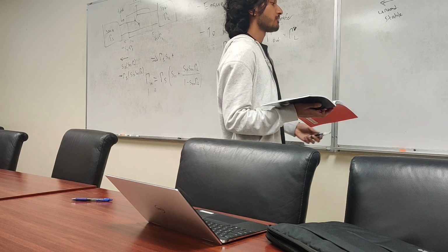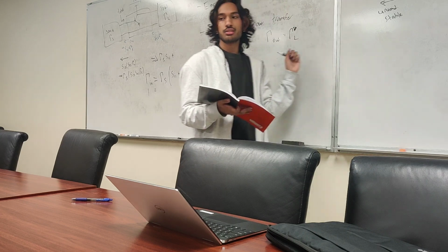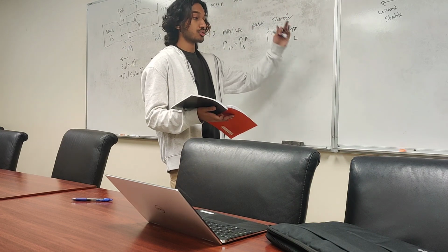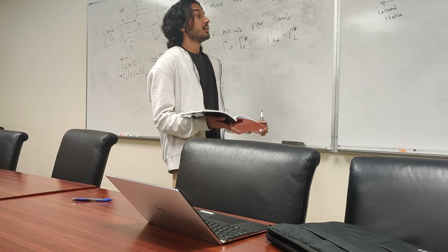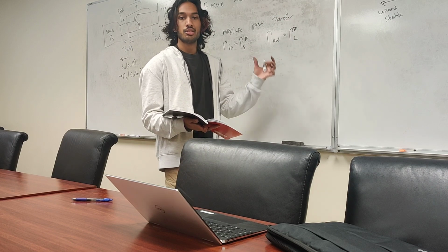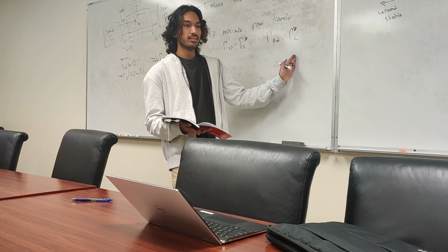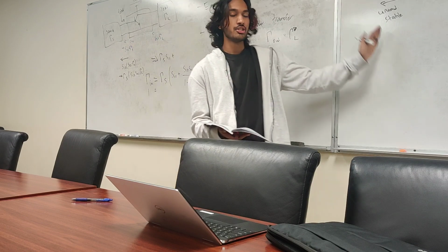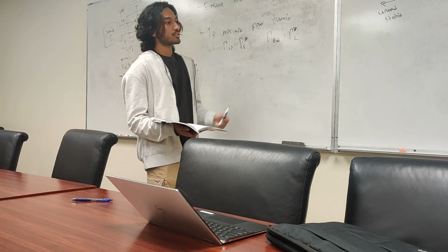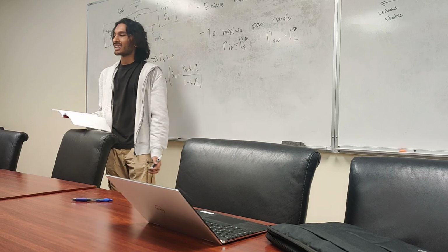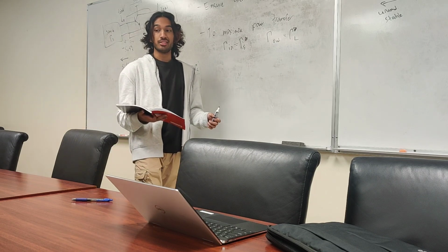I erased it, but you gotta remember that our source and load networks are all the way at 50 ohms. You put things in between to make sure you see 50, and then the other thing that sees your BJT. That other impedance is where your transducer function will be at maximum. That's not gonna be a 50 though, typically.